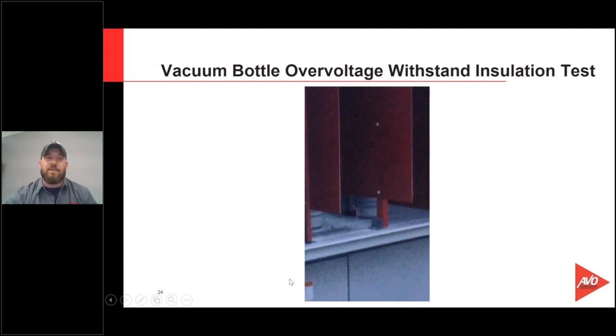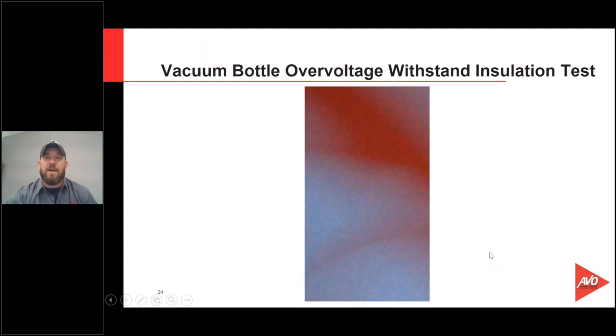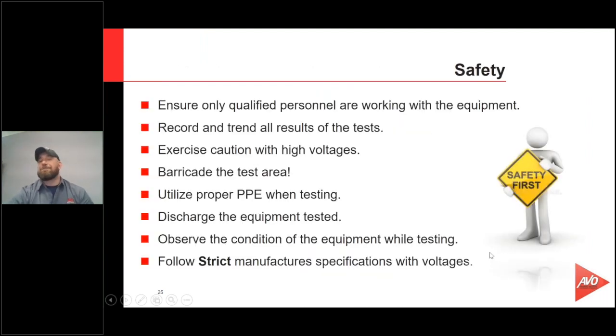I like to use just a little small wire, maybe 16 gauge, and run that wire from the outside of my insulator to ground, and you can see that leakage current rise with the proportionate rise in voltage. To give you an idea, I wouldn't always recommend that. We control it and it's safe, with lots and lots of safety. But a lot of times we're not going to see when it's going to fail, and when it does hit the fan, it's going to hit it hard. So speaking of safety, let's finish up on safety.